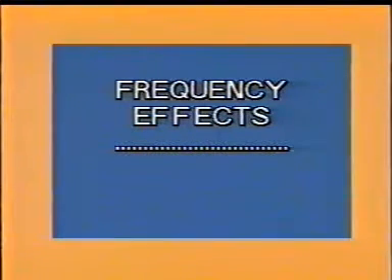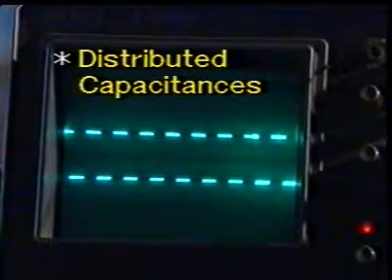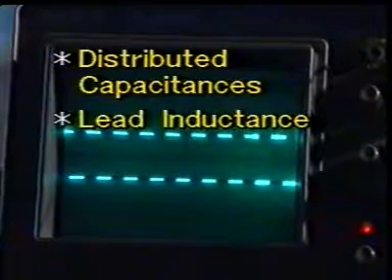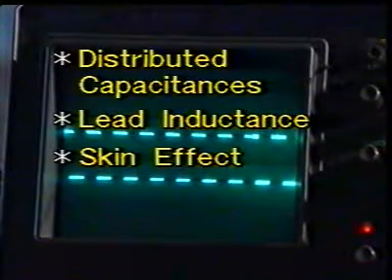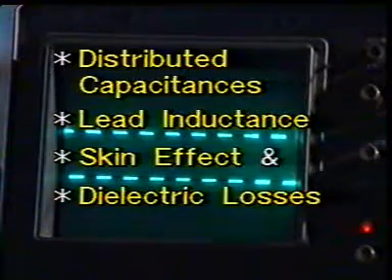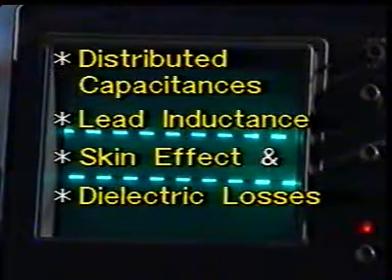Frequency response of a resistor is affected by distributed capacitances, lead inductance, skin effect, and dielectric losses.